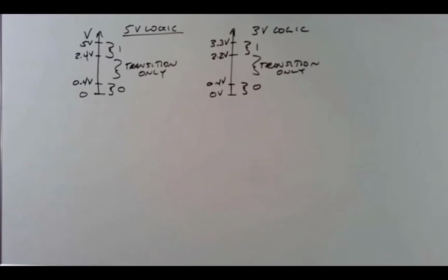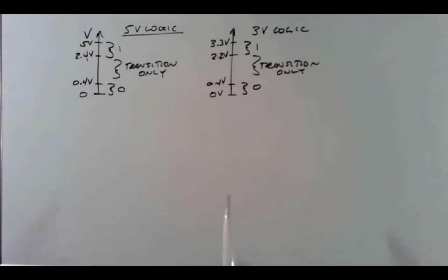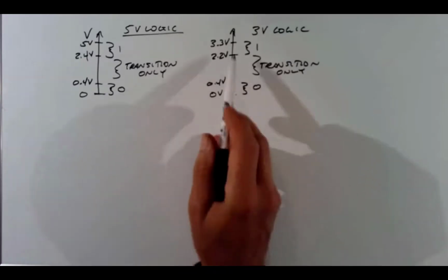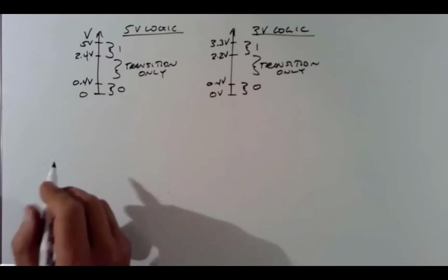Okay, so on the last whiteboard sketch, just to simplify it, I drew a single threshold. It's not really a single threshold to decide whether a binary value is 1 or 0 when you're looking at a voltage. It's actually 2 ranges. And outside of that, it's not valid. You can't tell. You have a broken chip or something's wrong with your circuit. Okay. All right. So this is how you represent a 1 and a 0. Let's talk about